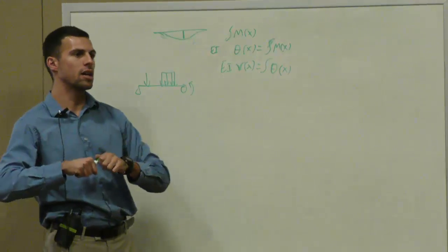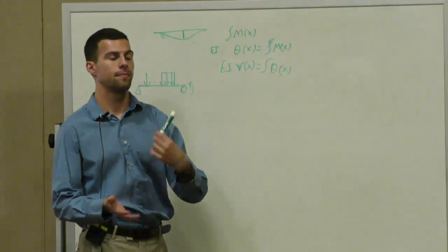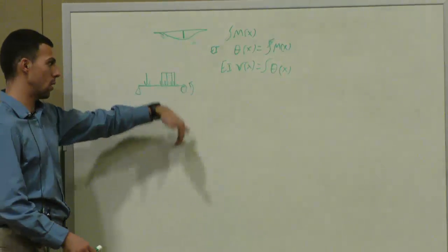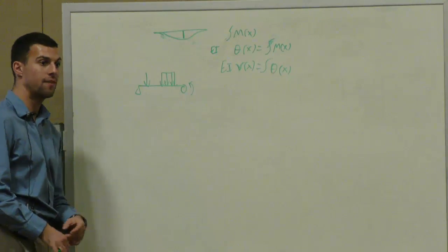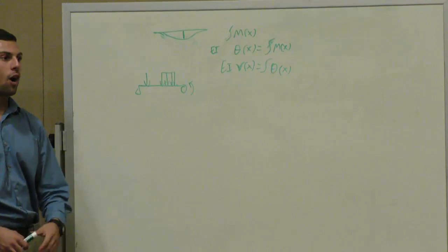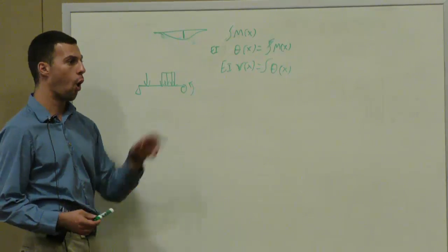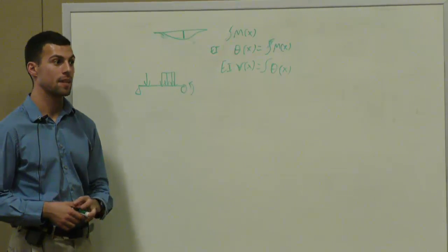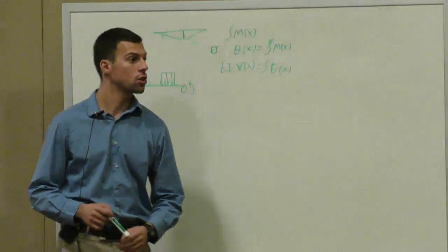It also makes a mess of those constants of integration, right? So every time we integrate, we have 1, 2, 3, 4 different behaviors of this moment. The moment equation behaves 4 different ways. So how many constants of integration do we end up with when we do 2 integrations for 4 moment equations? You end up with 8 constants of integration, way more than we want to solve for.